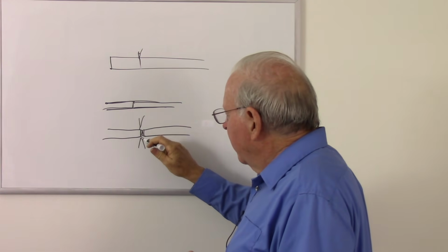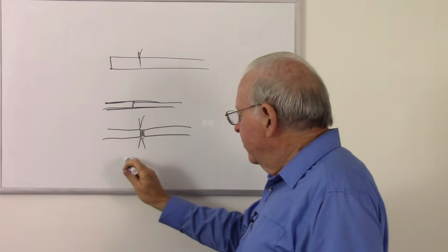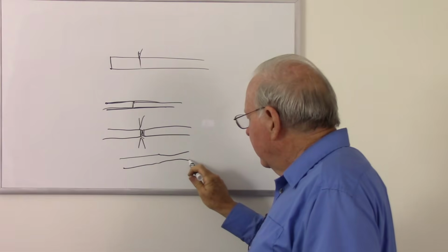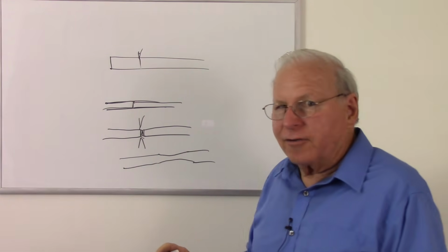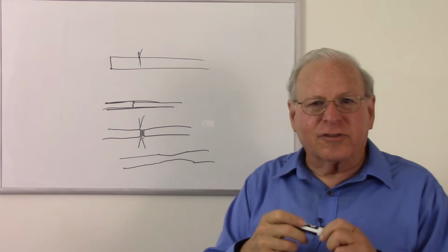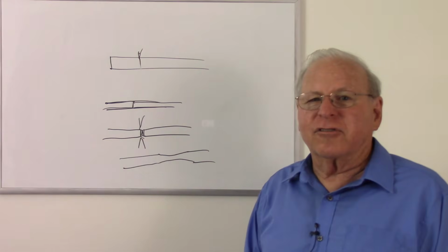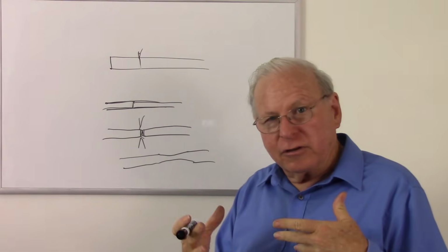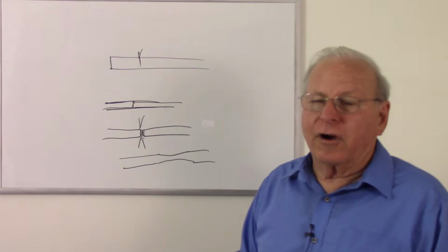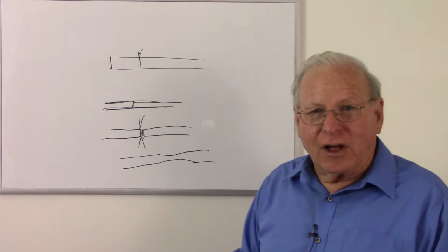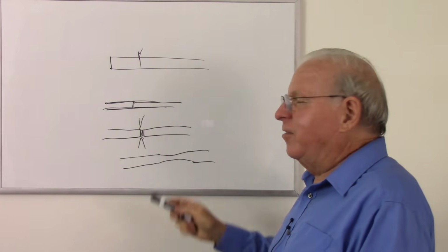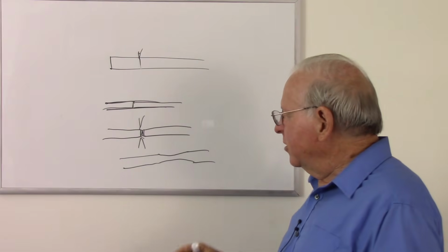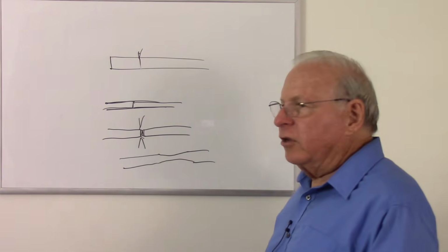But anyway, that spark melts the glass and it fuses together, and you have a slight little dip, but it's calculated to be just right. That's obviously exaggerated. You end up now with one piece of glass, so there's no possibility of reflection. So that's what a fusion splice is. Most likely, if you work with fiber optics, you're going to do fusion splicing, but the splicers start around $10,000 or something like that, so it's pretty expensive. If you need to do a few splices, you might want to use butt splices. You can buy them for a couple of bucks each. But if you're going to do a lot of splices, of course, you're going to use a fusion splicer.